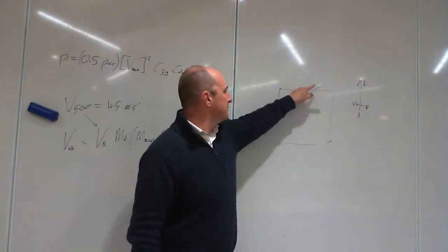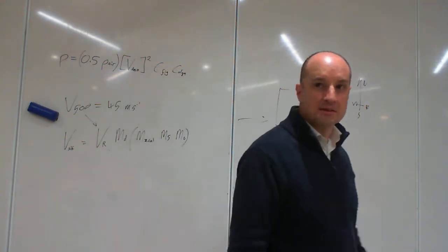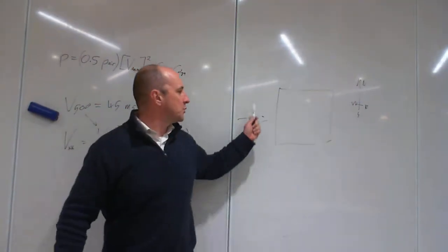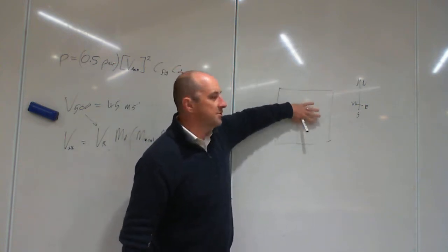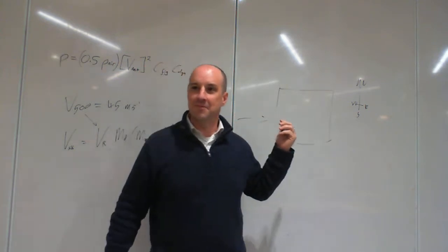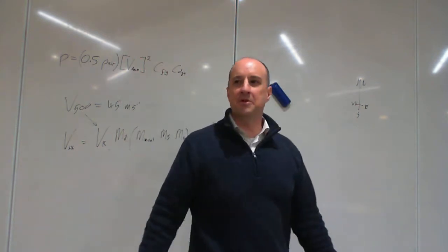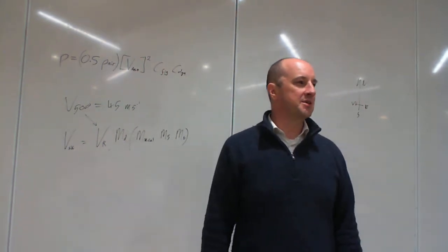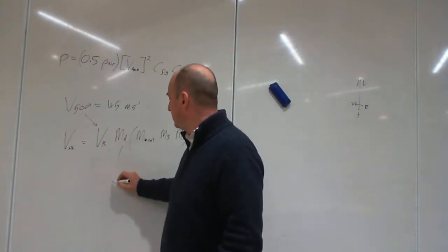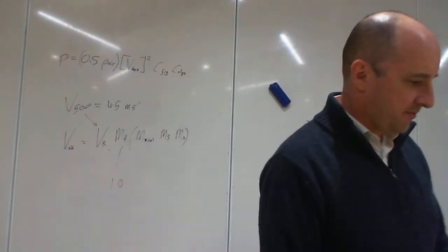So if you've got a big structure here, you have to make sure that you've got extra resistance from the western side rather than the other sides, okay? If you're designing a building and you don't know which way around that's going to be oriented, and someone comes along and turns the building 90 degrees, then that messes up all your calculations, okay? So normally, unless it's a big building where it's going to make a difference, and I'm absolutely sure which way it's going to be oriented, I say, someone might spin it, and we take MD as 1.0 all the time. Okay? There you go. That's MD out of the way.